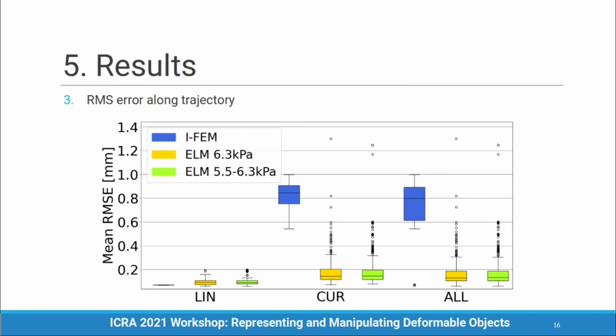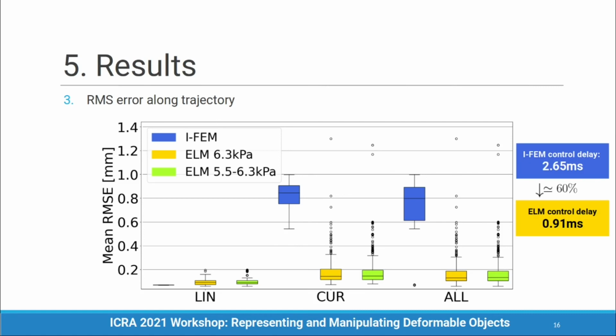For curved trajectories, the tip-to-target precision of the ELM remained small, while the IFEM kept a higher distance in average. Further tests are needed to address if this is an actual advantage of the ELM or if it's related to the additional entry point RCM objectives of IFEM. Timing comparison shows a 60% reduction in computational time needed to infer robotic commands using the machine learning approach.